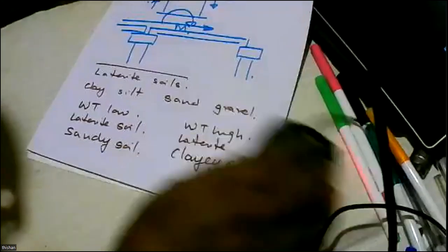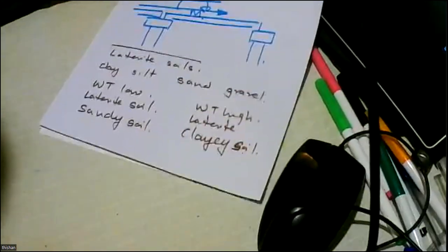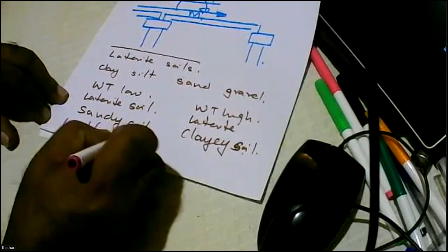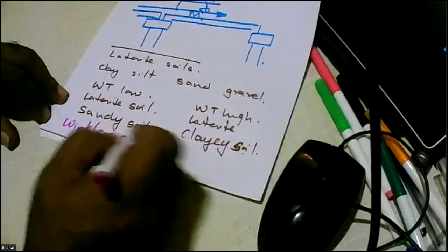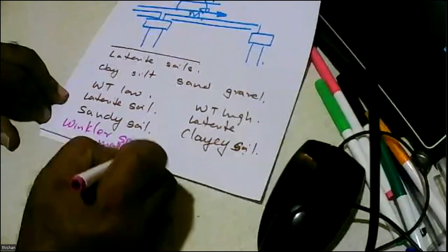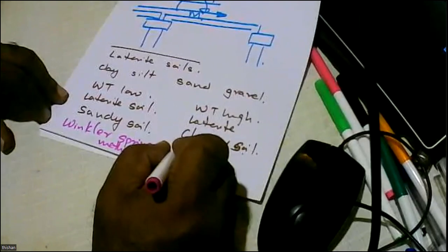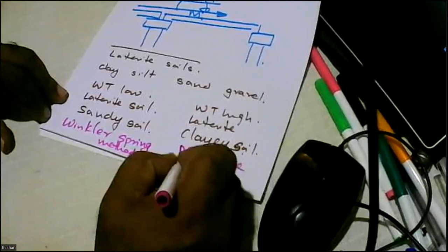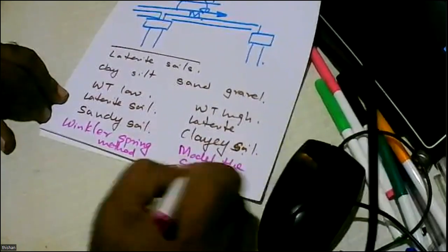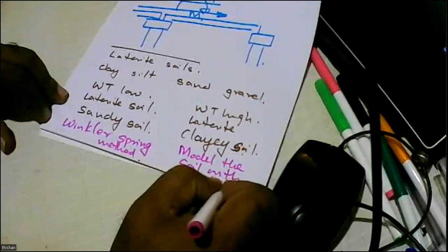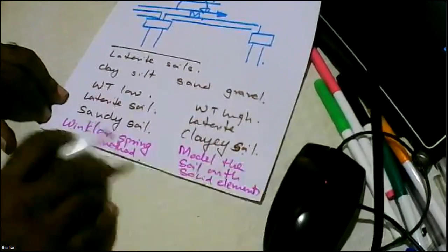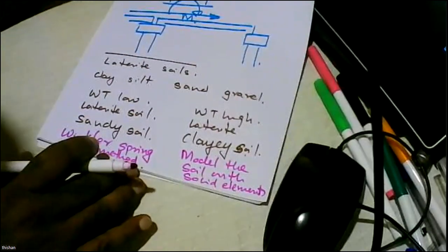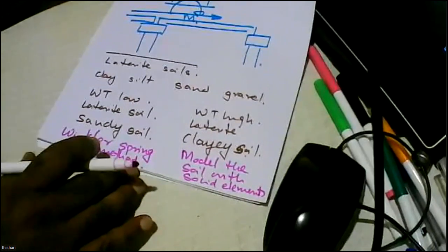And when we have sandy soil, we can use the Winkler spring method. When you have clay soil, we can model the soil with solid elements. So I'm going to show you the kind of theory that you should know to undertake this kind of modeling.